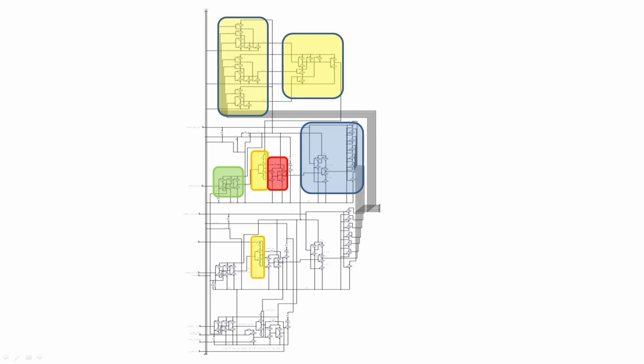Now this is the carry flag, that's the input control and the actual memory cell for it, and the control signal coming in so you can save your carry flag. And there's your output, again D0 and D2 to 7 are pulled to 0 volts, and your output goes on to D1 to give you a 0 or a 2 output. And down there is the C register, which we just saw in detail.